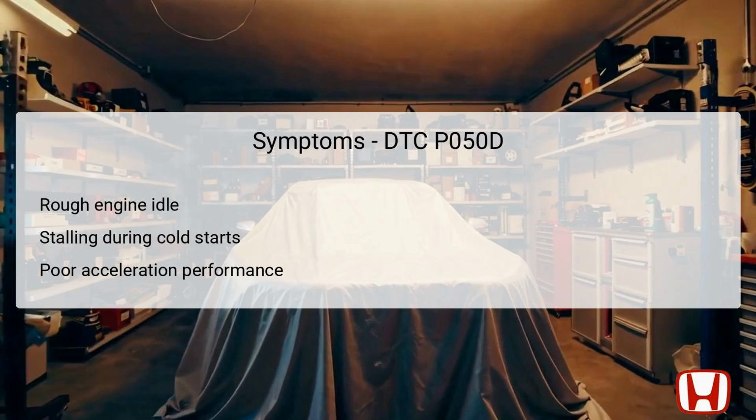When DTC P050D is present, several symptoms may manifest. One of the most noticeable signs is a rough engine idle, particularly when the engine is cold. Drivers may experience stalling during cold starts, which can be both inconvenient and concerning. Additionally, there may be an overall decline in acceleration performance, leading to sluggish vehicle response.